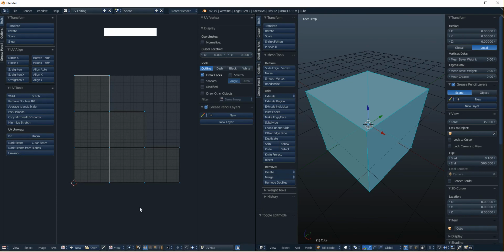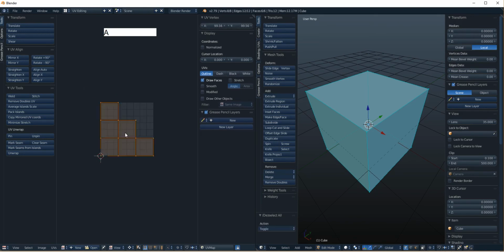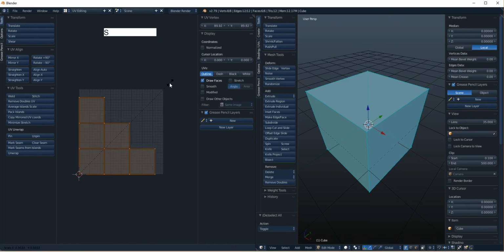Well, we have it here as well, so it can be set to 2D cursor, not 3D cursor, but in this case 2D cursor. And if I select, all the selection options are the same, right? In other words, the shortcuts for selection are the same. So I can scale to the 3D cursor, or I could scale to the median point, right? So it's scaling like that.